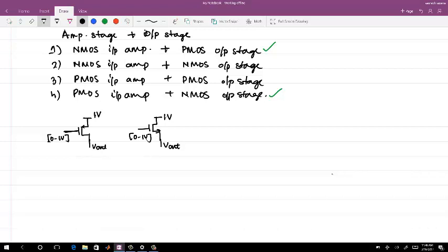The maximum you can go on the NMOS gate is 1 volt. In order to make it work, you have to come down a threshold voltage, and then V overdrive down. So you use both NMOS and PMOS regulation. PMOS regulation is mostly for oscillators where you want a higher output voltage to run at a higher frequency.